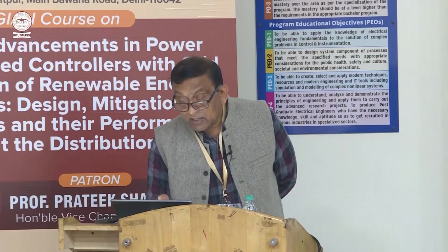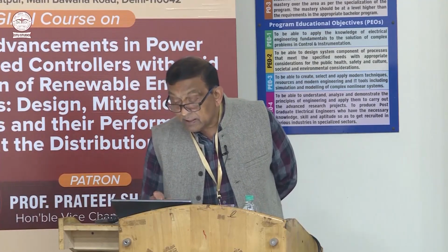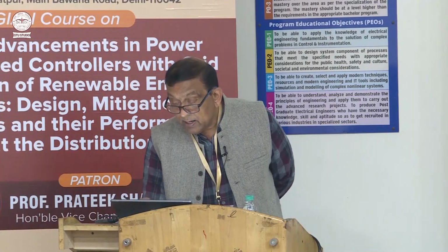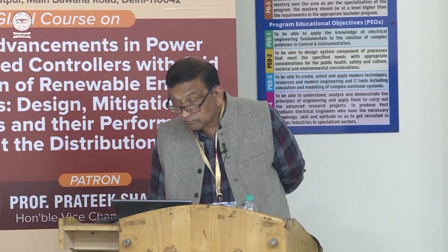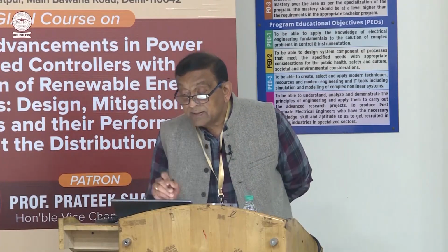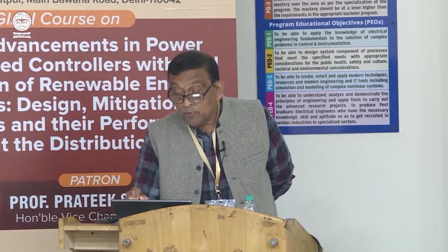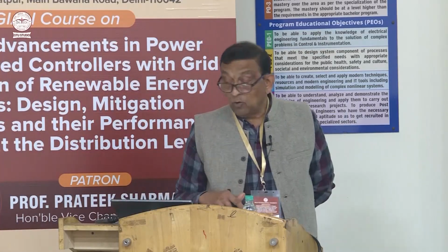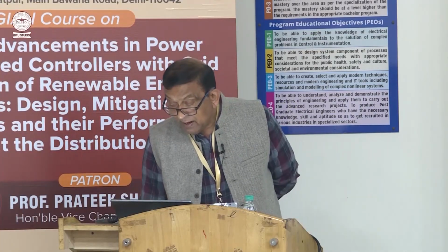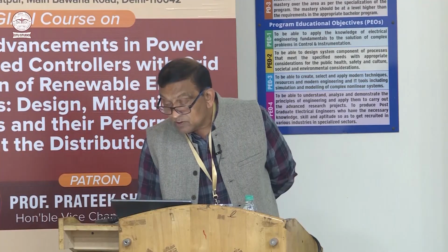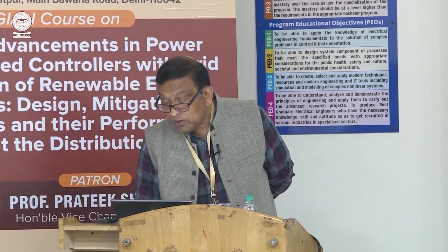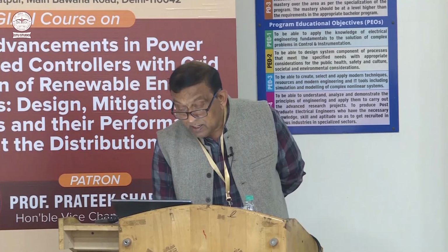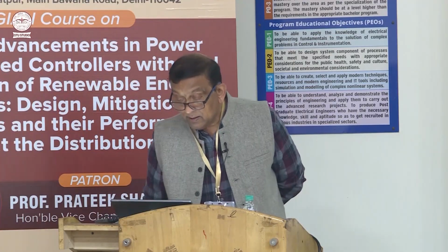Now we have another transformer, YD11. This is the characteristic, how the phases are shifted. YD11, it has this characteristic. Then we have delta zigzag, DZ0. 0 means there is no phase shift between the secondary side voltage and the primary side voltage, right? So we don't have time to analyze. Finally, you can see there is no phase shift between the secondary side voltage and the primary side voltage. You can see phase AB here, like this. There is no phase shift.